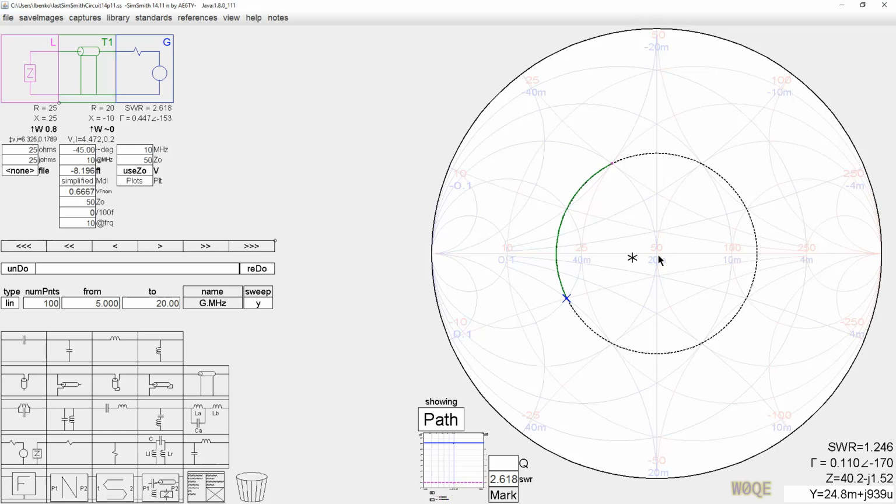One thing that's interesting about the Smith chart is it is not linear. The values near the center are much more expanded than the values out here. If we look at this, we go from 25 to 100, so 25 to 100 here. 2 times this much, 2 times this much this way. Here's 5 times, and if we go out here, it's 10 times, and this is 1,000,000 times here if we wanted to go out right to the edge, basically. So what we see is a lot more granularity in close. Well, if it's a 50 ohm system, we expect to have more of the action towards the center. So that's good.